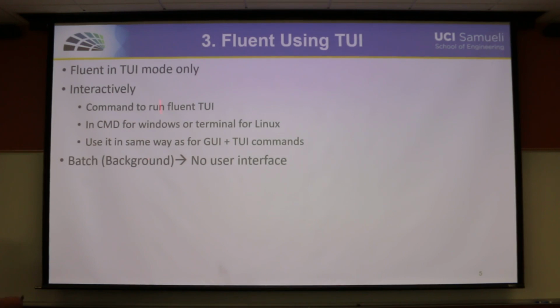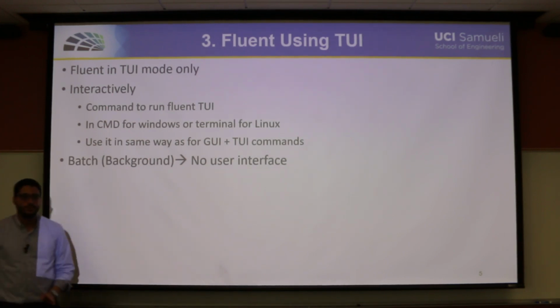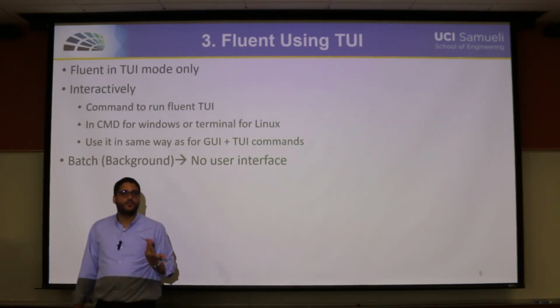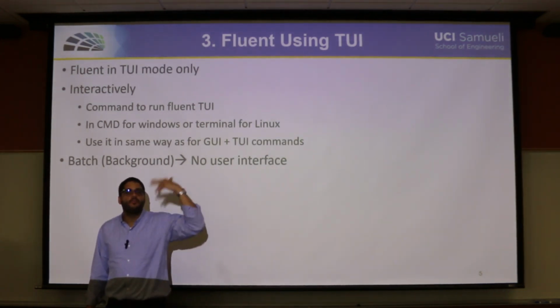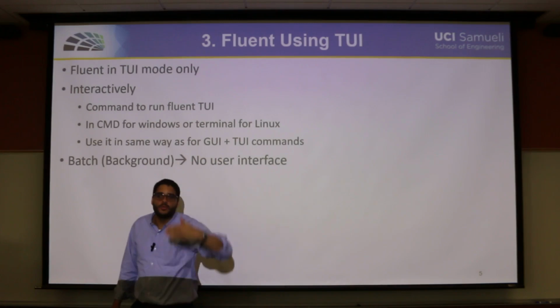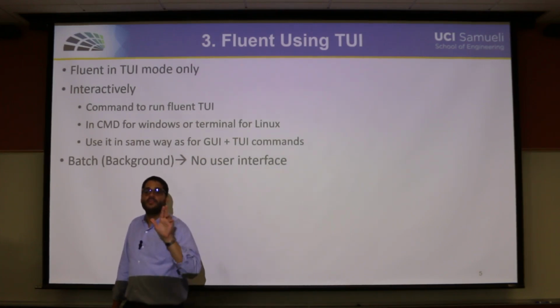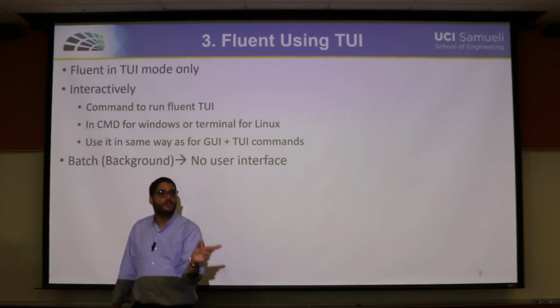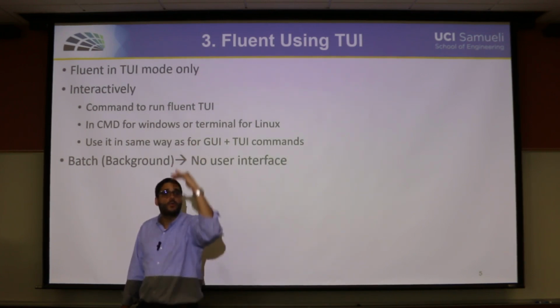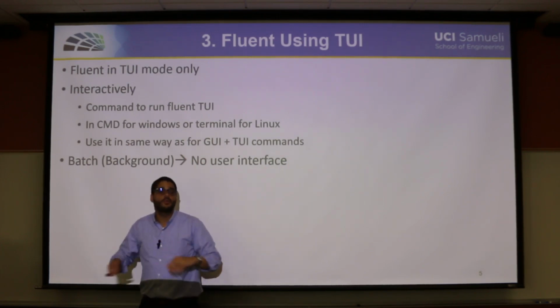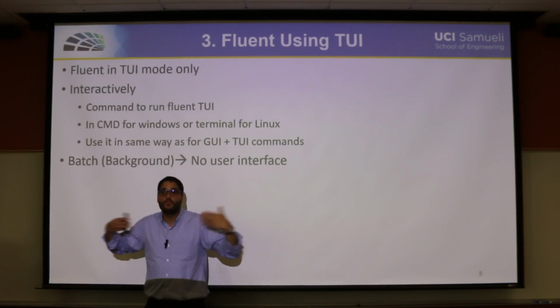Now, what if I would like to use it in TUI mode, but I don't want to interact with it? Even if Fluent is going to ask me a question, like, would you like me to overwrite? I need to have in my mind that sequence of orders that I'm going to implement, and have the corresponding reply ready and written in a sequential order, so Fluent executes step by step without any interaction from my side.